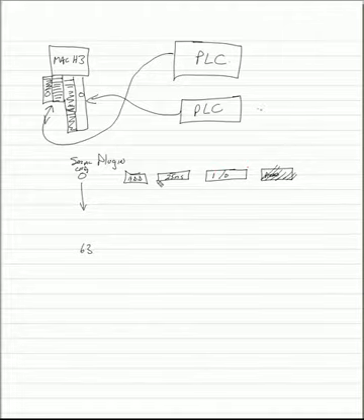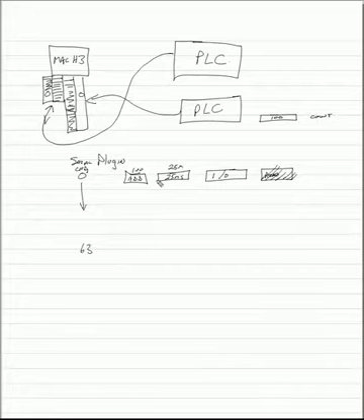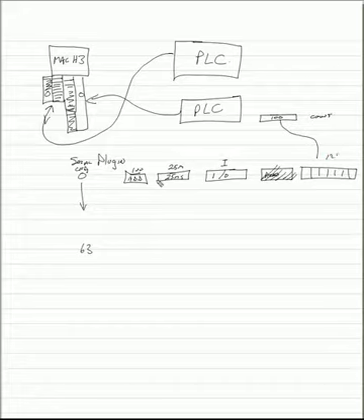Let's say, for example, that we know that in the PLC, address 100 is a count representing MPGs. We set up configuration 0 with address 100, refresh every 25 milliseconds, and say it's an input. At this point, every 25 milliseconds, the address in 100 will be sent to a buffer, which is in every configuration area, and the buffer is 128 words long.